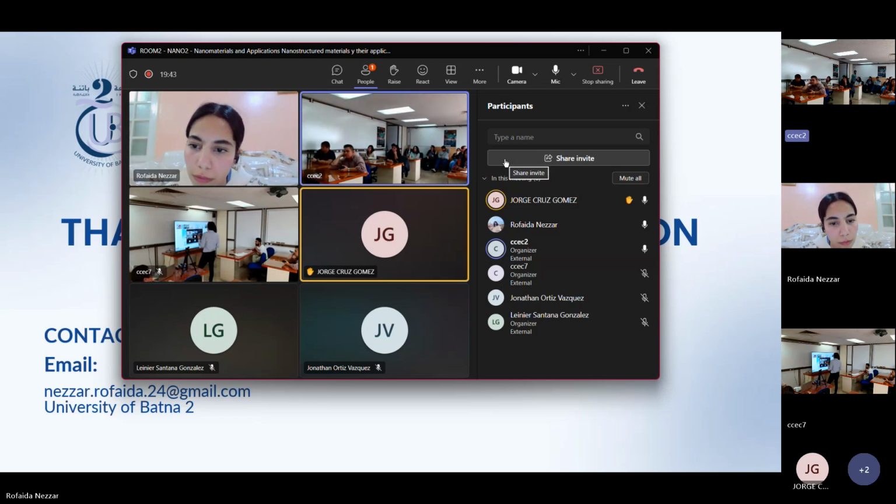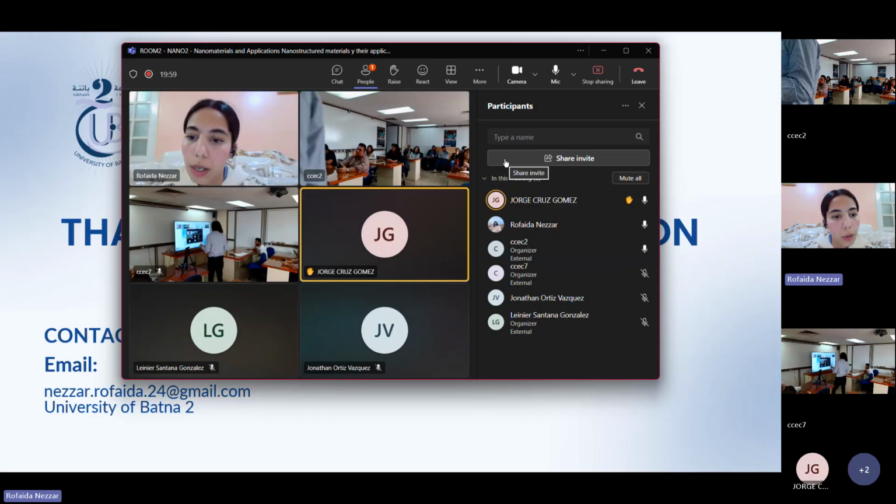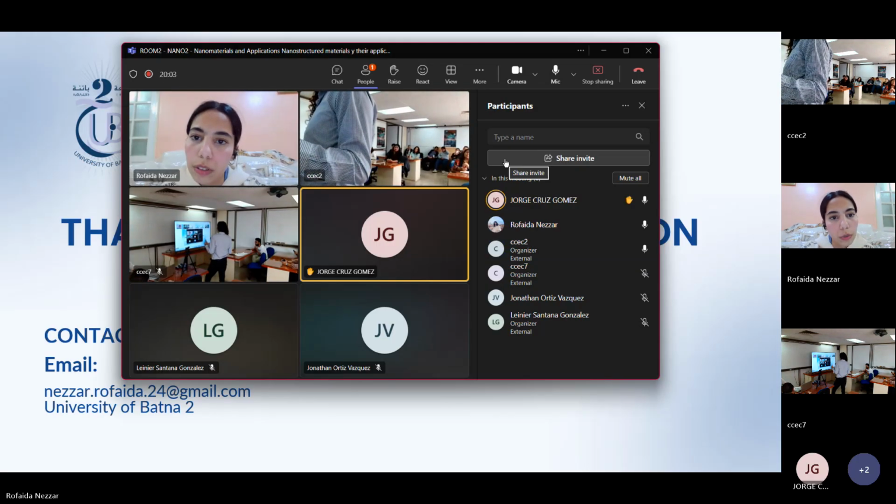What parameter do you need to control? I don't know, the pressure. Sorry. We have to monitor through the deposition. We have to monitor through ellipsometry or profilometry. Monitor the thickness of the film while in the deposition. Okay.